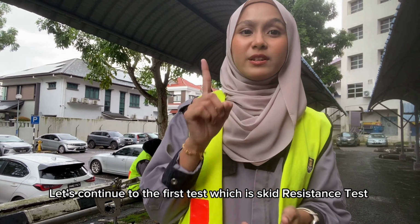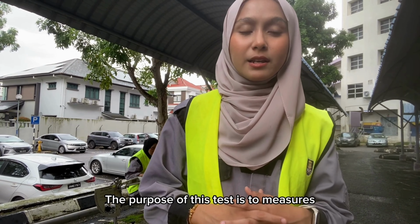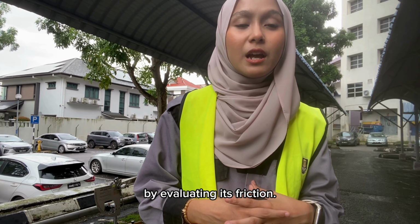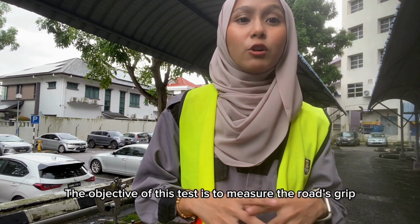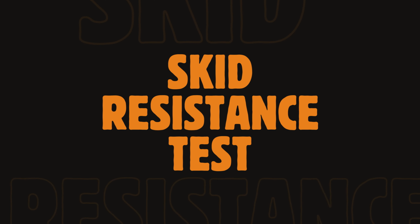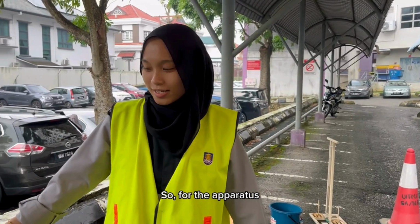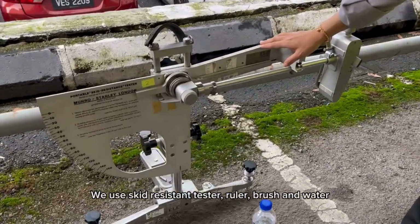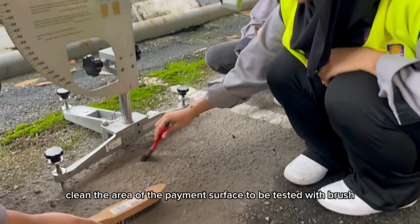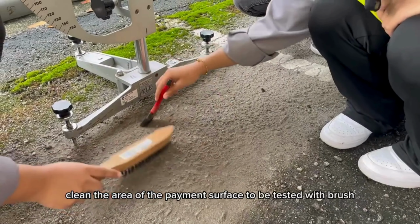Let's continue to the first test, which is the skid resistance test. The purpose of this test is to measure how well a road surface can prevent skidding by evaluating its friction. The objective of this test is to measure the road grip and prevent skidding. So for the apparatus, we use a skid resistance tester, ruler, brush and water. First, clean the area of the pavement surface to be tested with the brush.